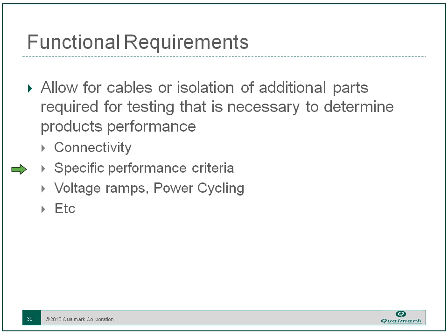One thing you do also need to worry about in HASS is making sure you use Teflon coated wiring throughout. Avoid the PVC. It over time can't handle the heat, even the heat of a typical HASS cycle, and it outgasses formaldehyde and various other nasty things. So it's best to stick with Teflon coated wire for all your internal wiring.